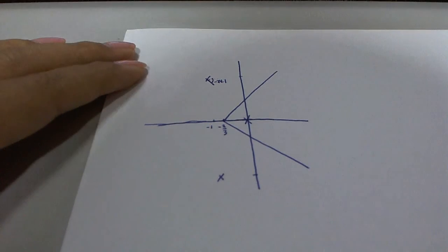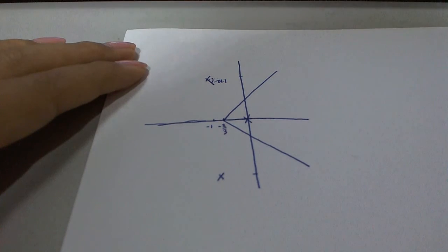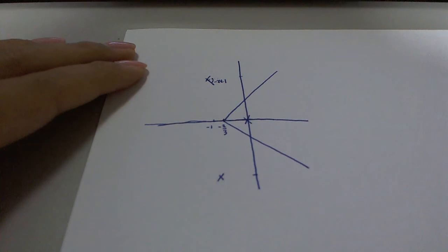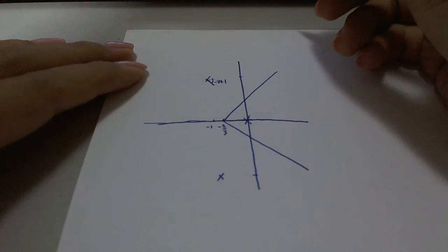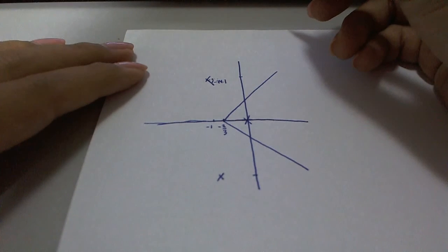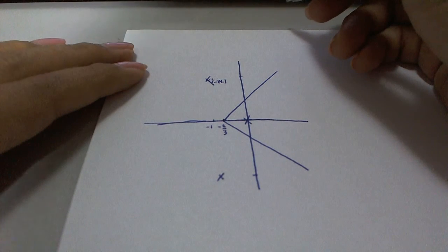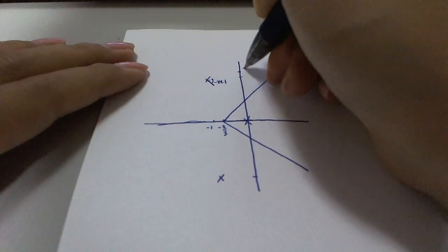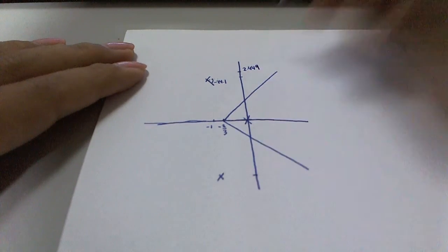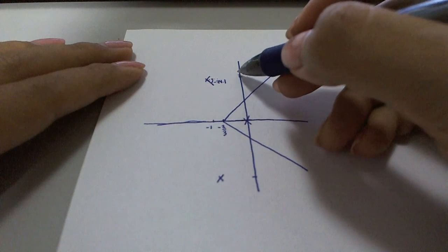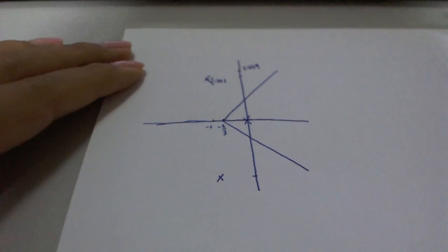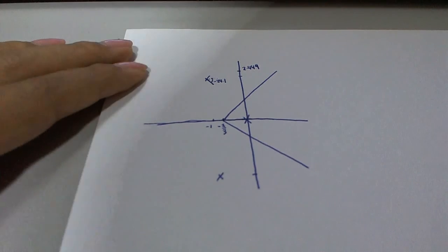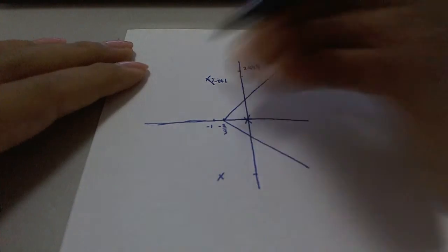And then lastly, we found the intersection of the root locus with the imaginary axis, which is at s equals plus minus j multiplied by 2.449. So here is about there, 2.449, and that is where our root locus intersects with the j omega axis. So now just complete everything.